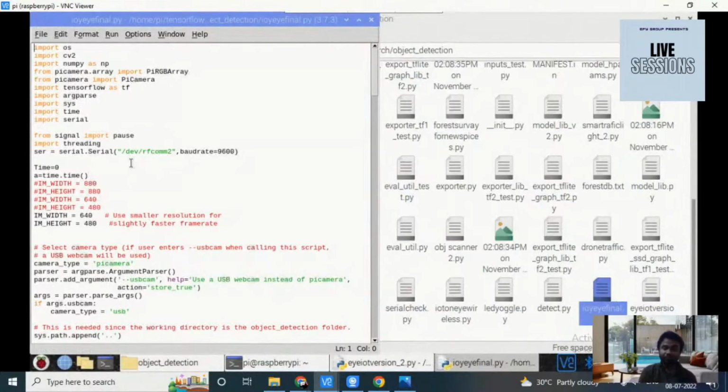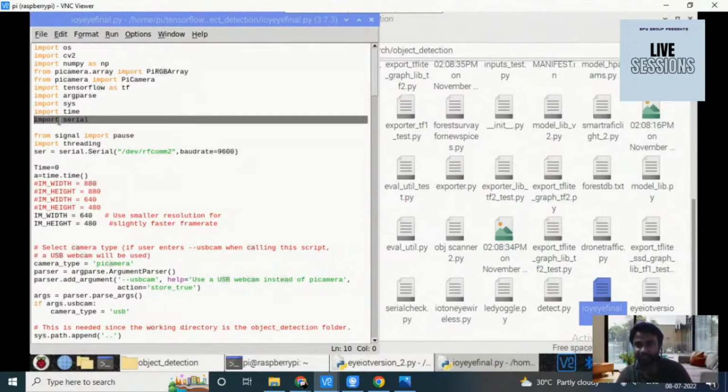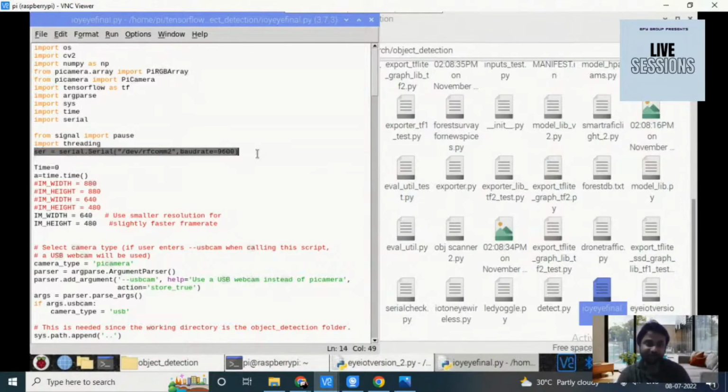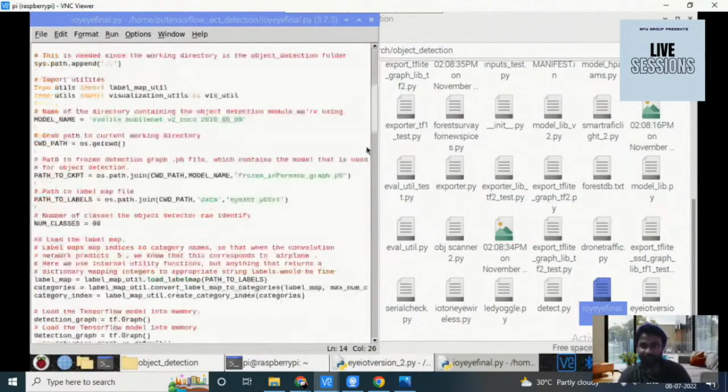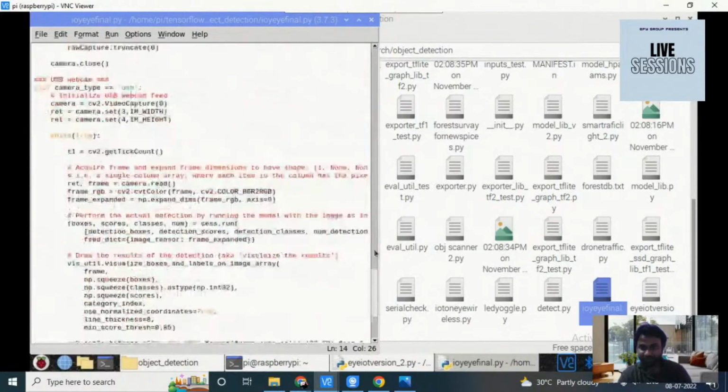After getting the Bluetooth module, we will program a microcontroller with the Bluetooth module so that whenever it receives a command, like B, from this RPI board, it will turn off the TV, or the toaster, or the refrigerator. Here I will set the serial port. Import the serial module, and then we will set the serial port for the Bluetooth module that is connected to the RPI board, along with its baud rate. And after that, we will move to the next part.